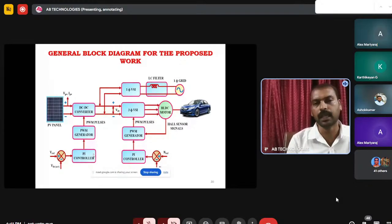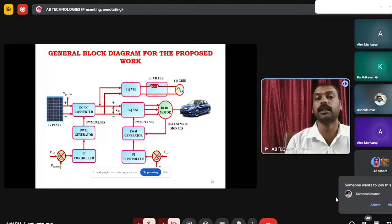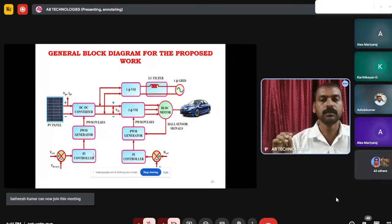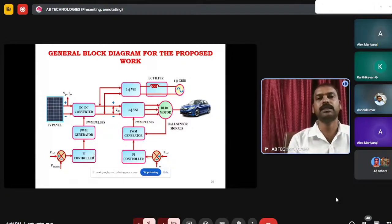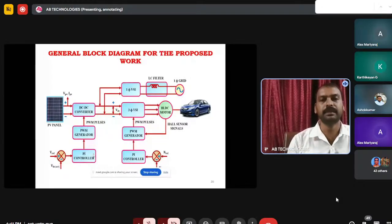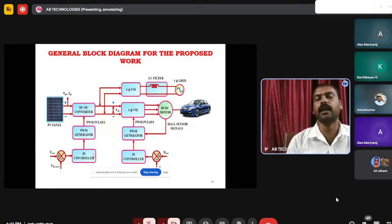In this MPPT algorithm, we are not taking any feedback on the output side. Only the input side we are taking. That means voltage stability is not possible, but power stability you can achieve with the MPPT algorithm. So for a standalone load, the MPPT algorithm is very suitable. But for grid connected or BLDC motor side applications, from my point of view, a closed loop controller is best.